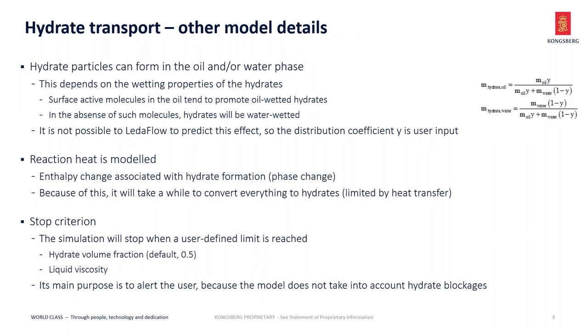So, some of the other model details. The hydrate particles can form in either the oil or water phase, or if you really want to, you can also let them form in both phases, but that is kind of unusual. Whether the hydrate particles form in the oil or water phase mainly depends on the wetting properties of the hydrates. If you have surface active molecules in the oil, then this would promote oil wetted hydrates.